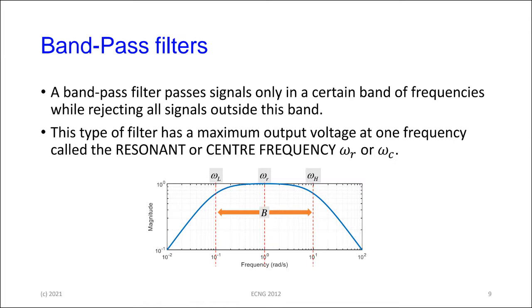The truth of the matter is that almost all electronic circuits, from very low to very high frequency, are inherently bandpass filtering in their behavior. But what we're talking about here is intentionally making a circuit that does this. The response is the figure below here. This is what the frequency response looks like. It passes a range of frequencies between some lower and some higher frequency.